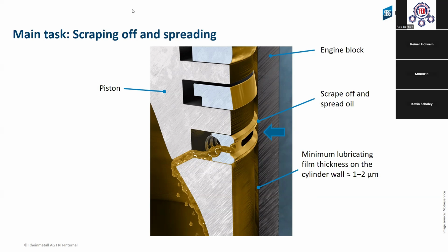thickness of oil film for the second and the first ring, to have lubrication between the piston rings and the surface of the bore of the cylinder liner. And the scraper ring must scrape the oil down. You also see the drainage behind the piston rings. There's a spring behind, and then you see the oil can be returned inside the piston. And this can also be different.